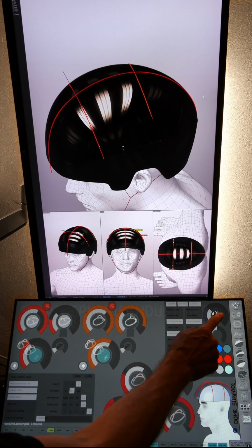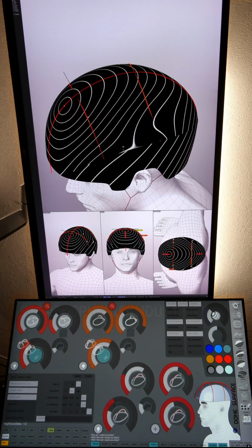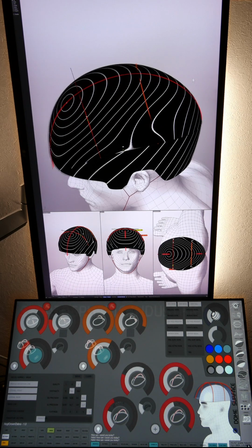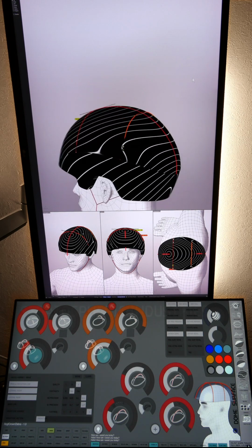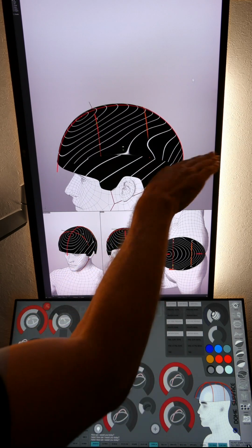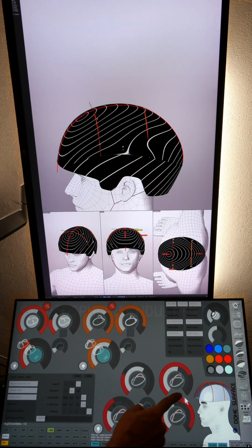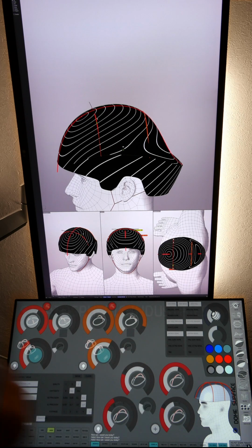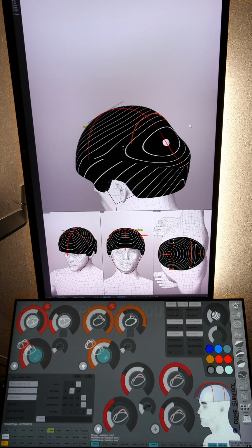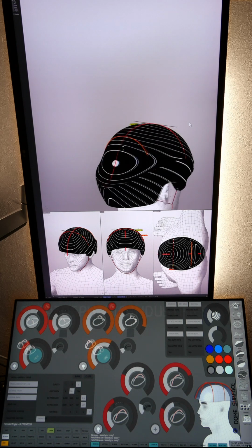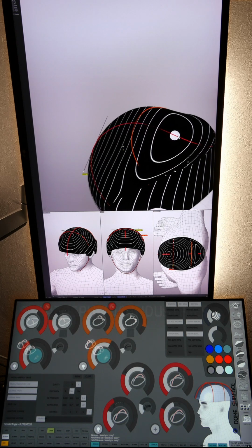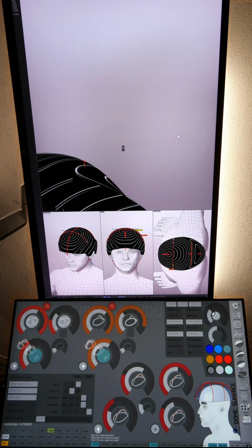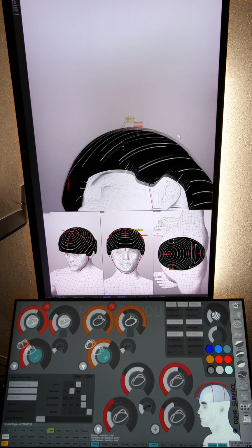Let's visualize that with the isophoto display. Now we see the kind of curvature that's happening there with the control lines. If you were to go entirely negative again on the back, you would have a concave section. So let's just try that for a second. Oops. Ugly helmet, but sort of the fireman look there. That's what happens with the curvature display when it goes concave. Actually cut through, you can see right there, into the inner shape, the inner headform surface.